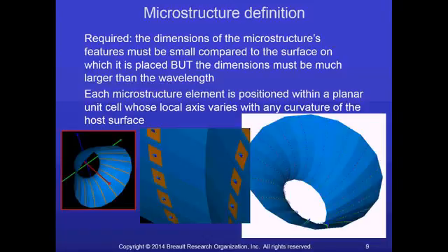You only define one unit cell. ASAP determines where the rays would hit on the unit cell. There aren't millions of unit cells stored in memory because that defeats the purpose of trying to give you rapid ray tracing. But this basically allows you to see the orientation of the cells across the surface. And you also could simply ask ASAP to display what the local axis is for each of the array elements as they would go across the surface.